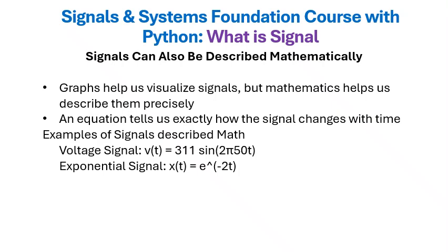We have different AC systems or power systems in different countries. In countries like Pakistan, India, Bangladesh, Malaysia, etc., we have the 220 volt signal. 220 is basically the root mean square value, and the peak value of this signal is 311. That means this signal goes up to a maximum of 311 in the positive cycle, and similarly the minimum value is minus 311. So this signal fluctuates within this range. We saw this graphically on the previous slide, whereas here it is represented by the mathematical equation.